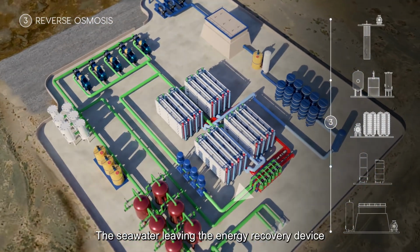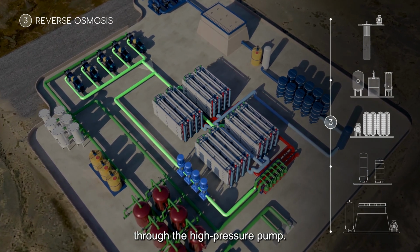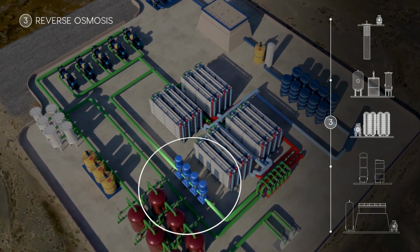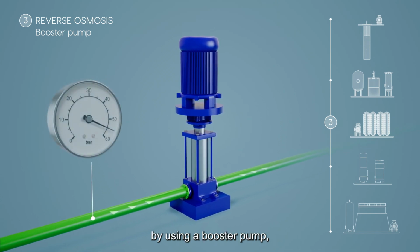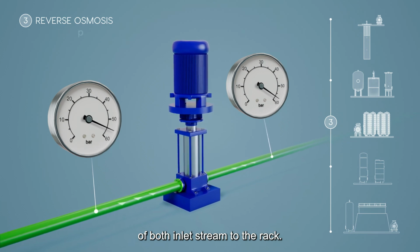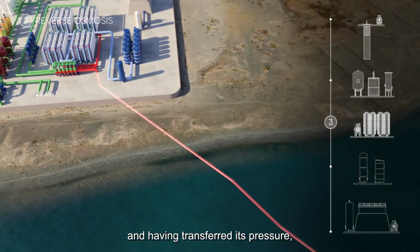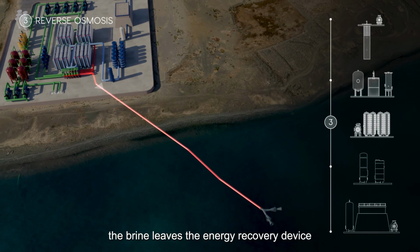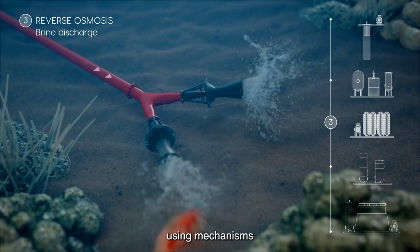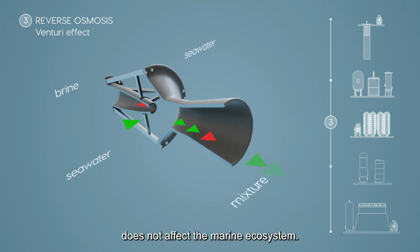The seawater leaving the energy recovery device does not have the same pressure as the seawater leaving directly through the high-pressure pump. Additional pumping by using a booster pump is needed to equalize the feed pressure of both inlet streams to the rack. After passing through the isobaric chambers and having transferred its pressure, the brine leaves the energy recovery device at low pressure and is discharged into the sea, using mechanisms that ensure its correct dilution and dispersion, so that its discharge does not affect the marine ecosystem.